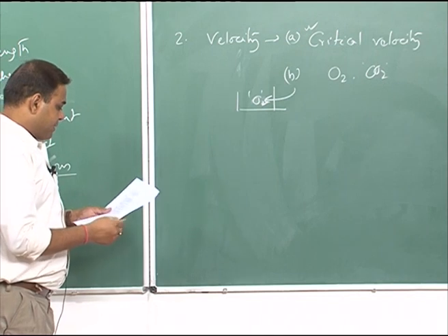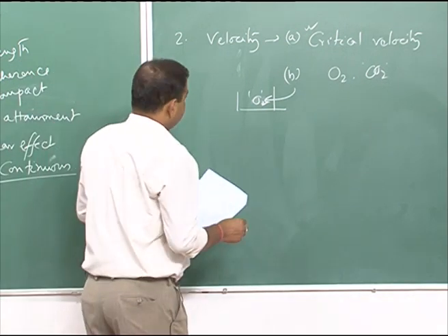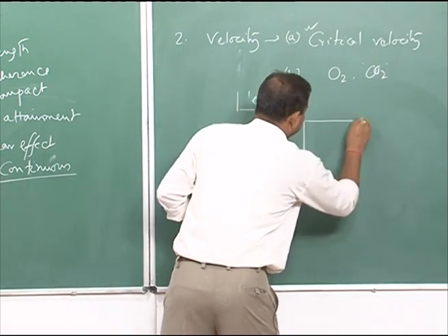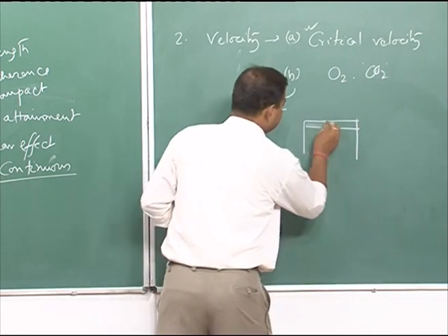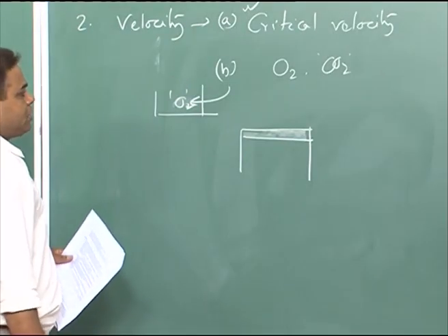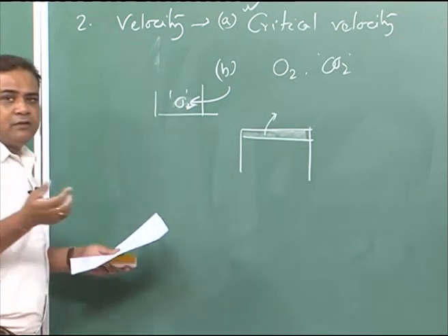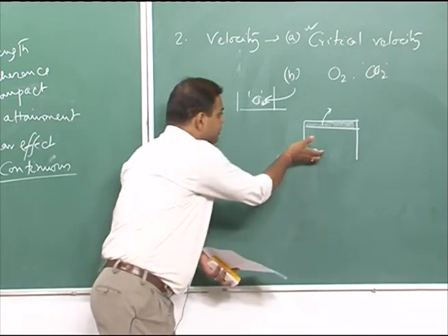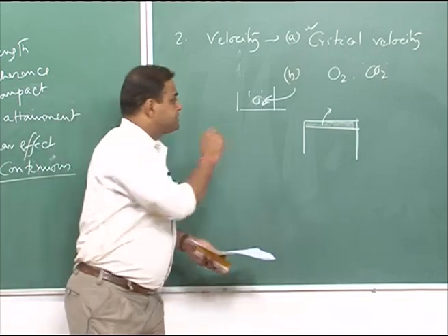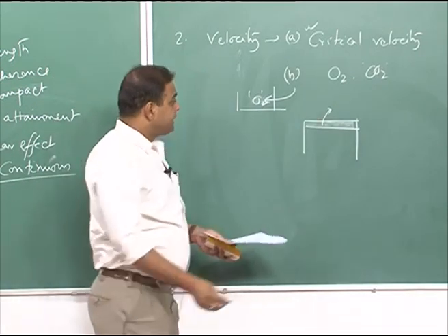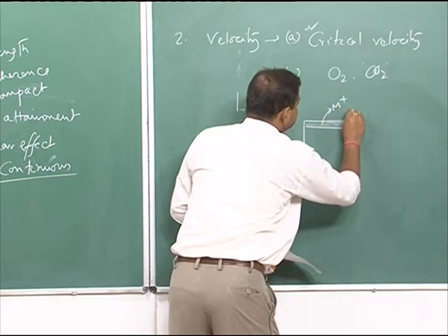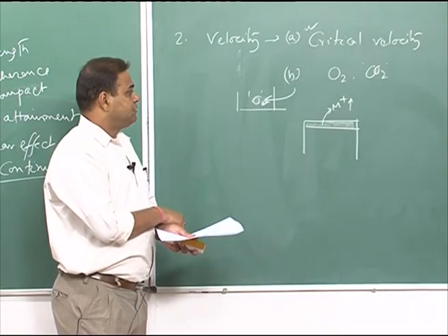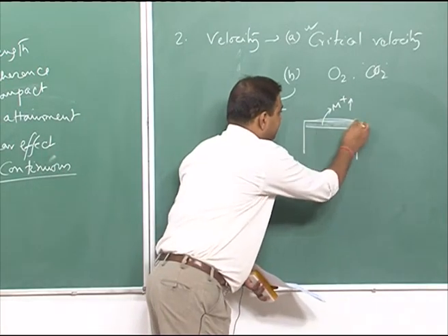And then it increases the diffusion or transfer of ions. Let us say I have a particular metal surface where a passive layer is forming. If it is a stagnant solution at that particular temperature, metal dissolution is of course taking place, but once the metal ion concentration reaches some critical value, because of the solubility effect of that passive layer, the metal ions will form a passive film